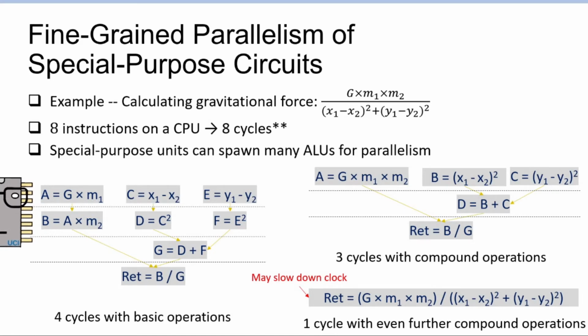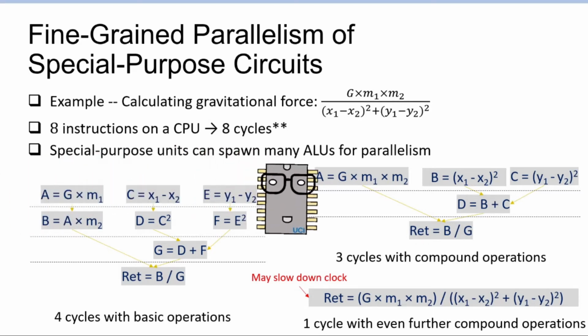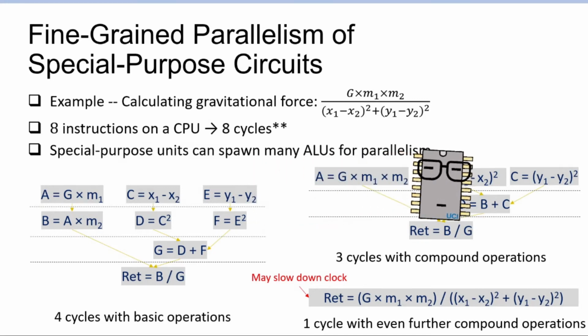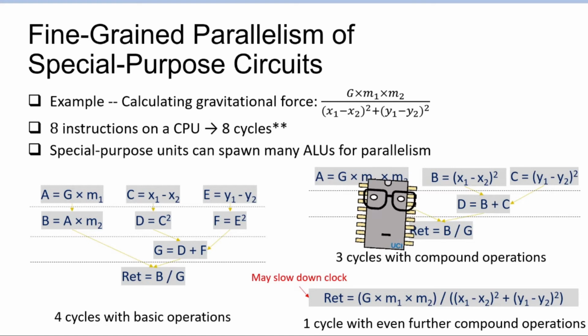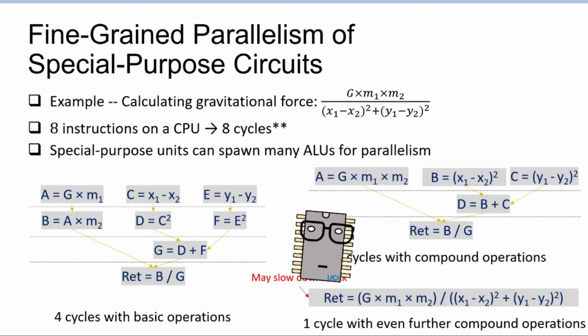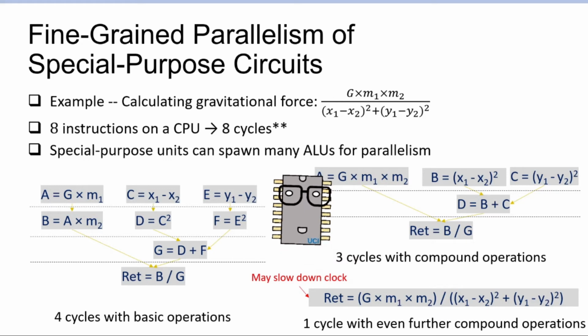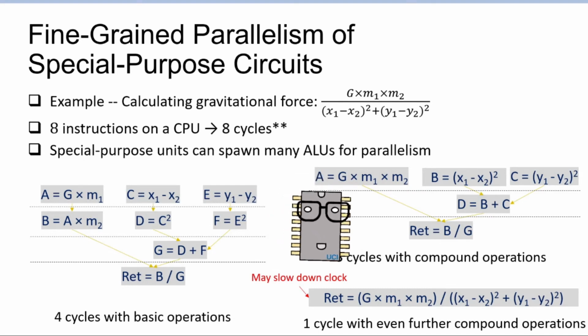But if these individual ALU operations are lightweight enough that the latency internal to these things is short enough, then maybe we can merge these things together inside a single clock cycle so that we can do more operations per cycle. This can give us lower latency, potentially lower chip resource utilization as well, because we don't have to have pipeline registers between these pipeline stages.